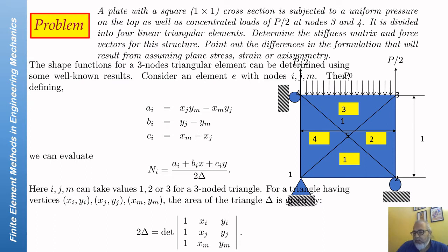strain triangles. A generic constant strain triangle, let's say constant strain triangle number 1. So the first task and the most important task is to calculate N, which we have seen is a 2 cross 6 matrix, and B, which we have seen is a 3 cross 6 matrix.